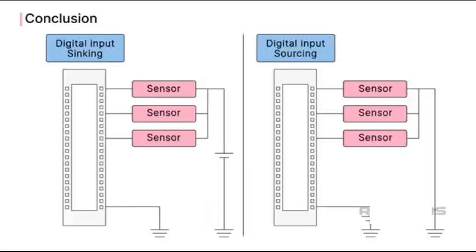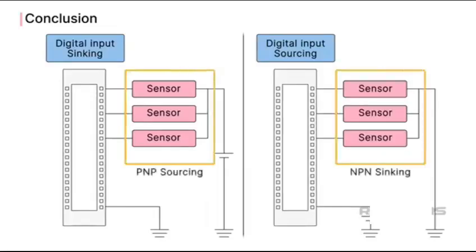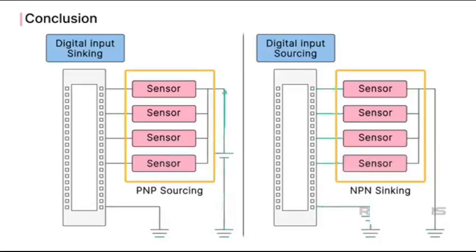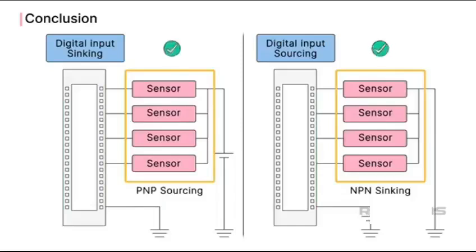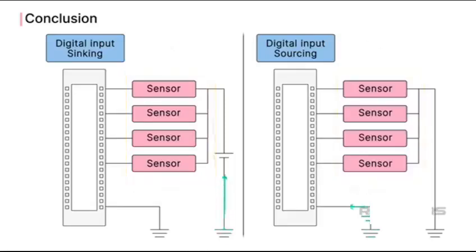Most modern PLCs allow the flexibility to wire NPN or PNP, but may require doing so as a block, based on a shared common. Checking out your PLC common wiring scheme is key if you are troubleshooting or adding to an input-output card. For design, planning ahead will make sure cards, instruments, and commons match. Thus, matching the design to the application is more important than debating over whether PNP, sourcing, is better than NPN, sinking. In the end, having planned out wiring is much safer and less costly.